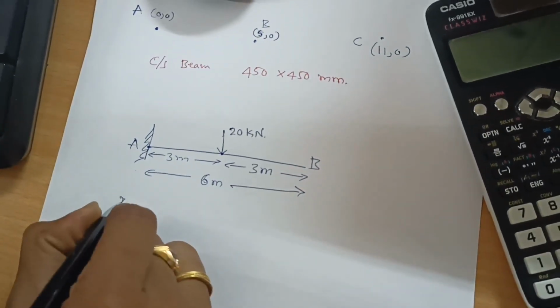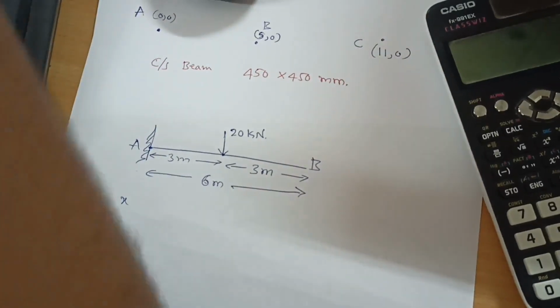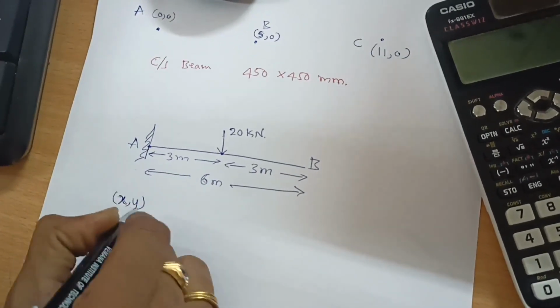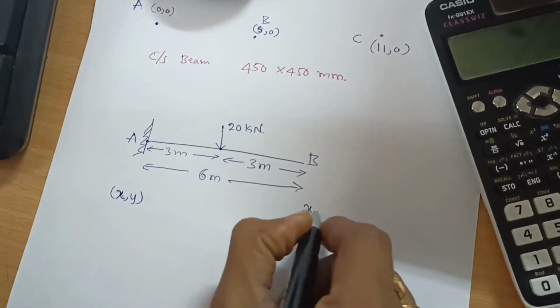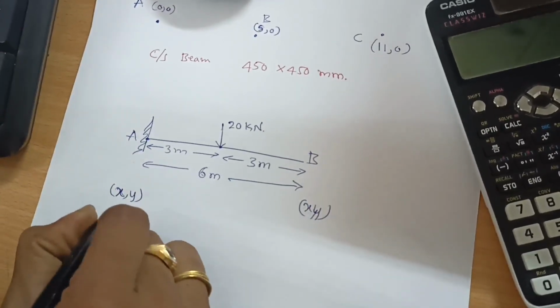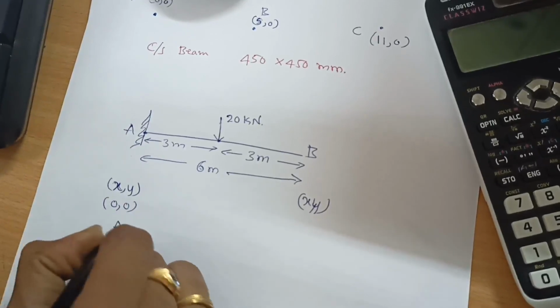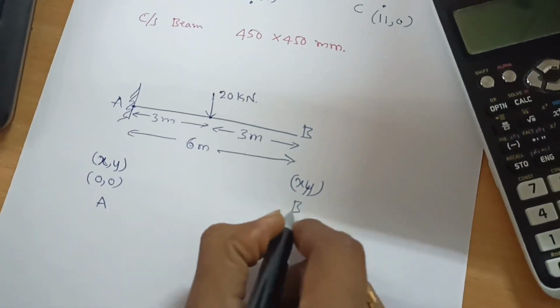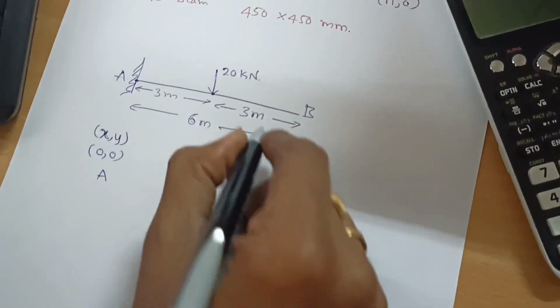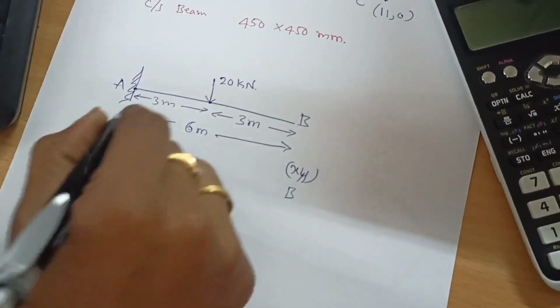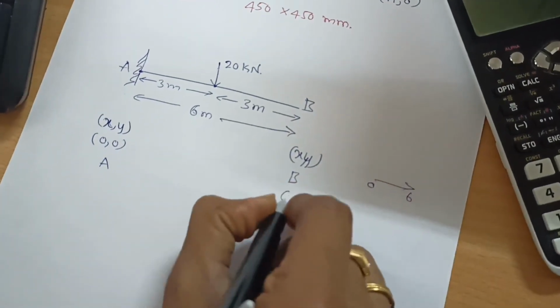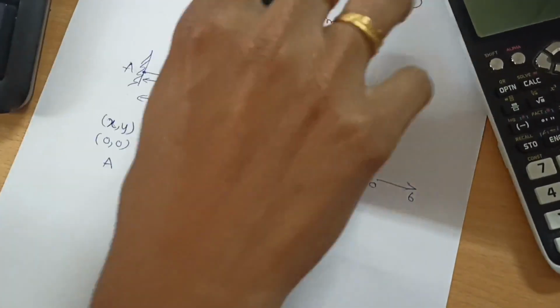This software runs on coordinates. We are going to create the nodes in the Cartesian coordinate system, that is x, y. Right here, the origin I am going to select. Node A is our origin, that is the 0, 0 coordinate. Then similarly, node B, or joint B, has x, y of 6, 0. From here the x axis runs 0, 6, like that. These are the nodes.